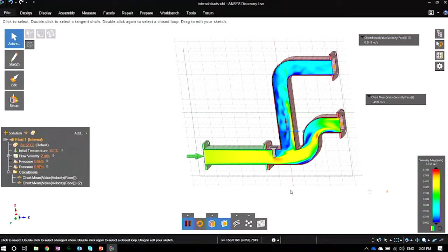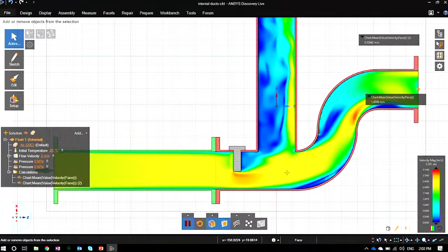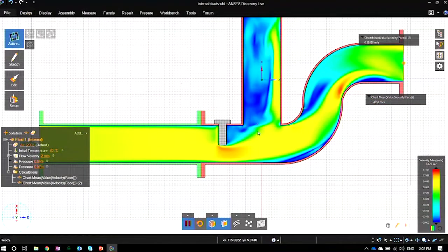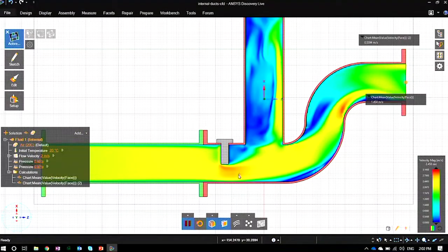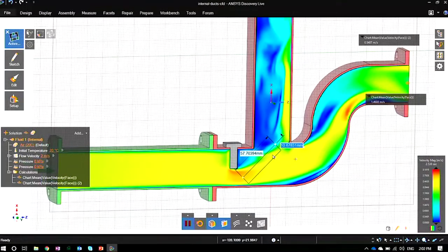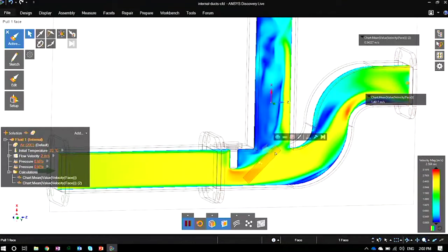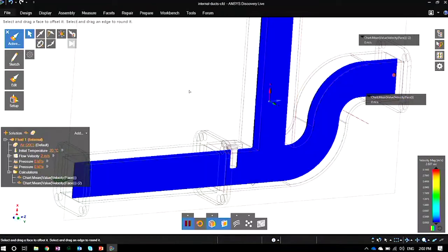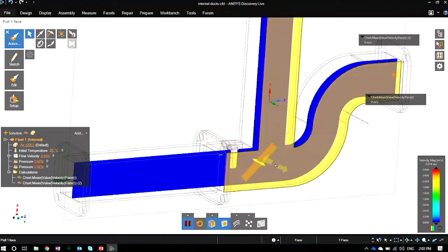Again, like we were talking about, it's a direct modeler, so we can start to make some sketches around here. I've got these design components that allow me to sketch. So on the actual component, I think I might design a baffle. Maybe it's going to start around there. I don't know, maybe the angle's like that and it's that big. I can go from a 2D component into something that's 3D very quickly, so I can pull that out, and just go back.